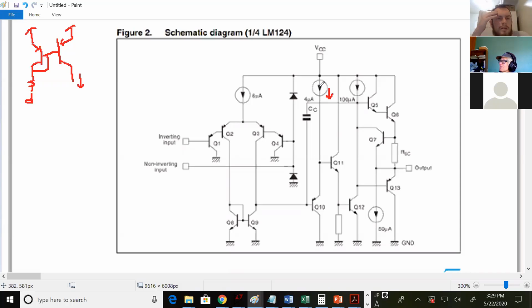Change the voltage in the collector. So here's kind of an unconnected question. If you change the voltage and the current doesn't change much, is that a big resistor or a little resistor? If you change the voltage and the current doesn't change, yeah, it's a big resistor. Okay, so if you're right here, what resistance do you see looking up? RO. RO, okay. So that's a big resistor, but how could you make it even a bigger resistor?